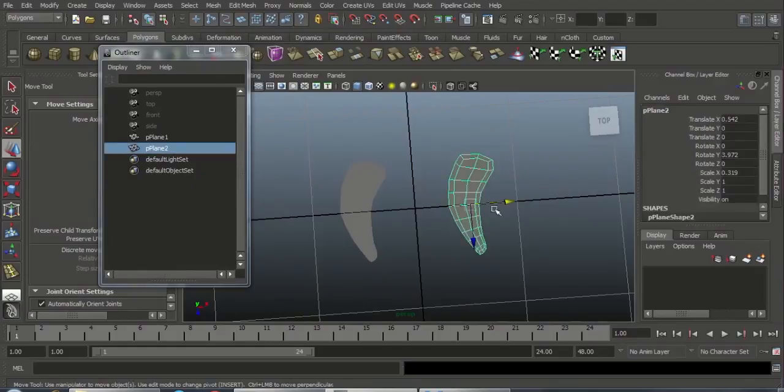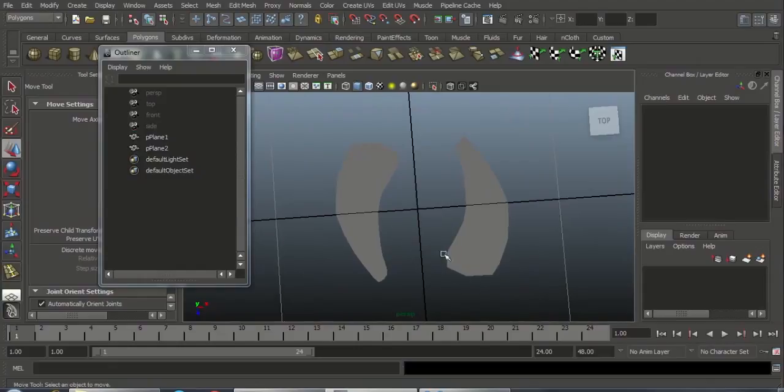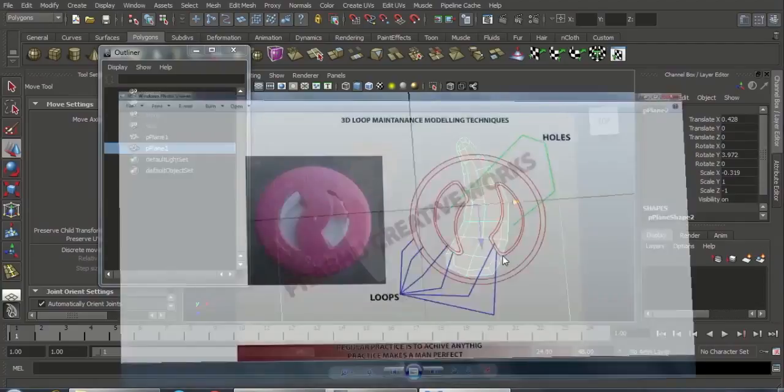See here, in the X axis, I got the X value. So press the minus key before that value and press enter. So that means it will flip this side. I want to flip in Z also, so press minus and press enter before the Z value. So that means the mesh will be flipped over. I will move it a little bit forward, like this. So that means you got this curve S shape here, as mentioned.